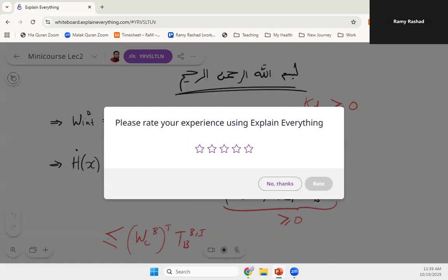When I had the variable impedance controller, the controller part was not passive. The robot itself, the rigid body part, was passive because I canceled the gravity. And then I was left with the environment, which was also passive, but the closed loop system was not passive. But this is not why it broke. It broke because the environment just disappeared. So it has nothing to do with passivity itself.